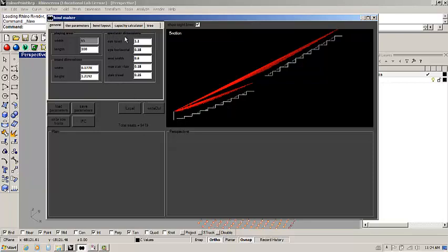There are some basic, fundamental parameters: height of the eye level above each row, horizontal position from the riser, width of the seat, maximum stair riser, maximum stair tread. You can see that it generates the profiles for the steps in between. We're going to look at loading and saving parameters, writing IFC files, writing DXF files, and also writing some data directly to Excel.